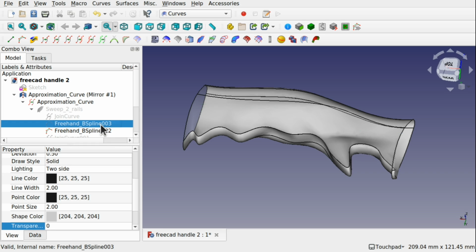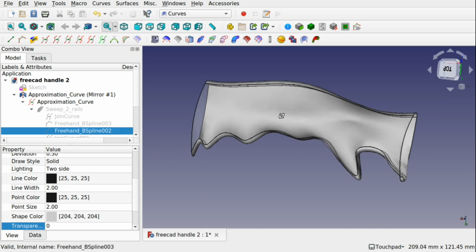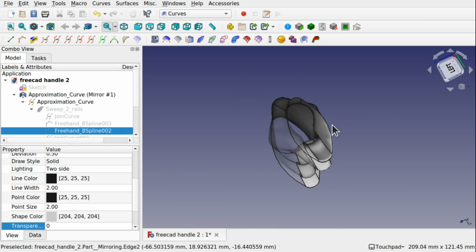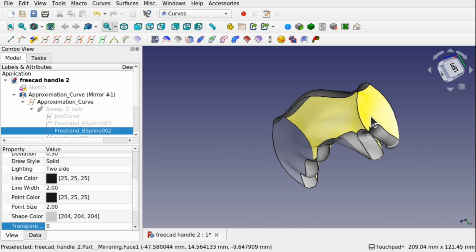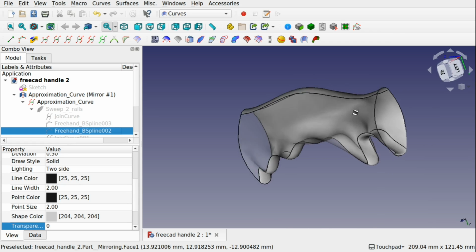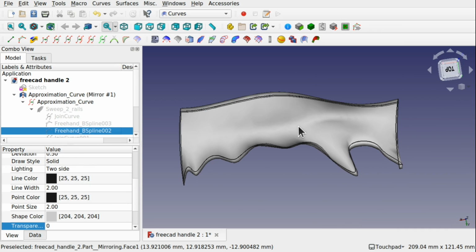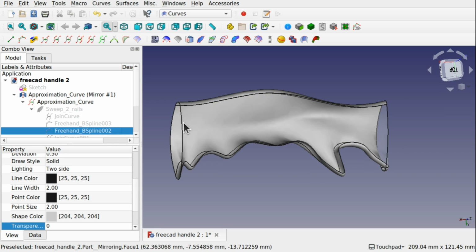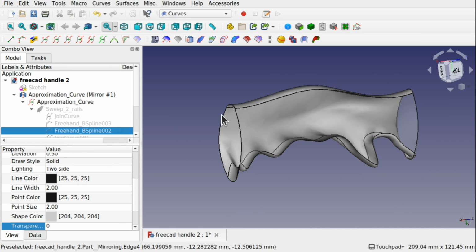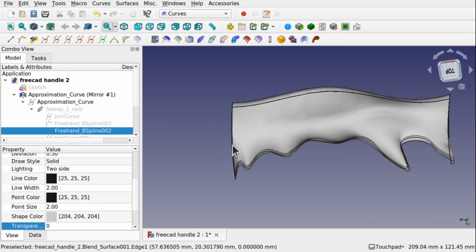Now the question is that we've got all these, how do we make this solid? Because before, in the previous video, I created a cap on here, but it was not parametric. I want that to be parametric. The way we do that is make these planar surfaces. So a planar means that they have to have all the vertices along one plane.